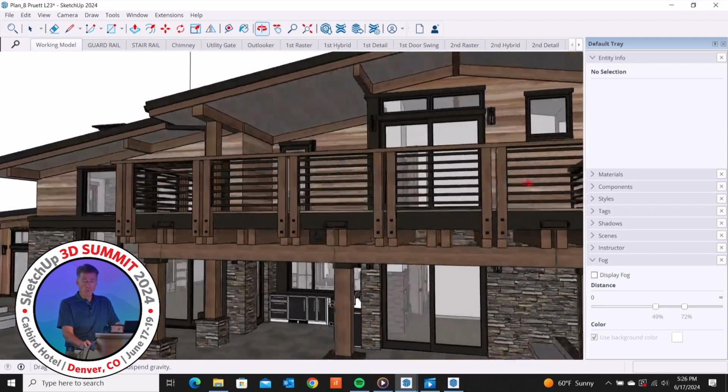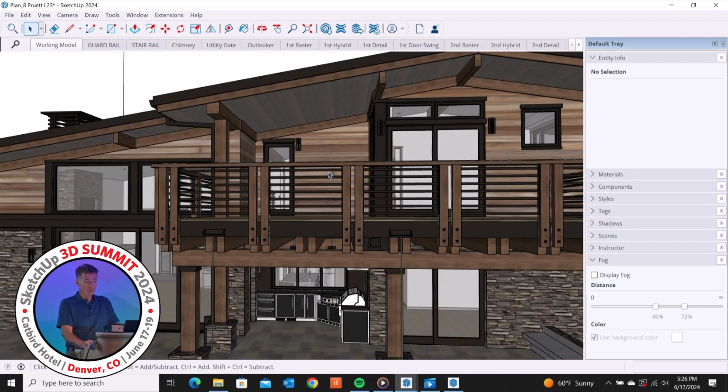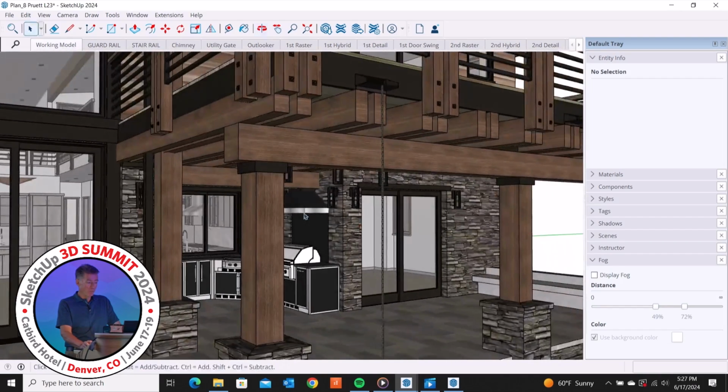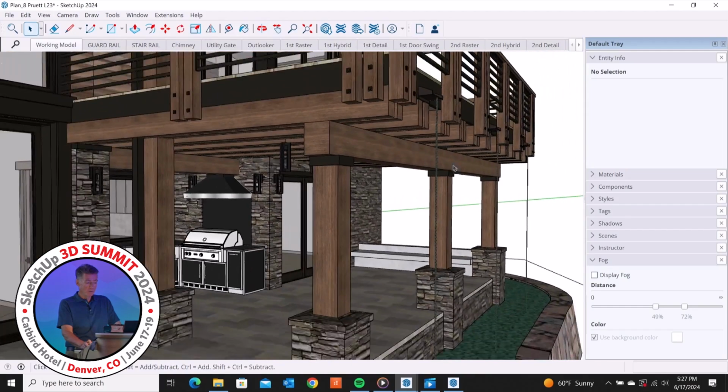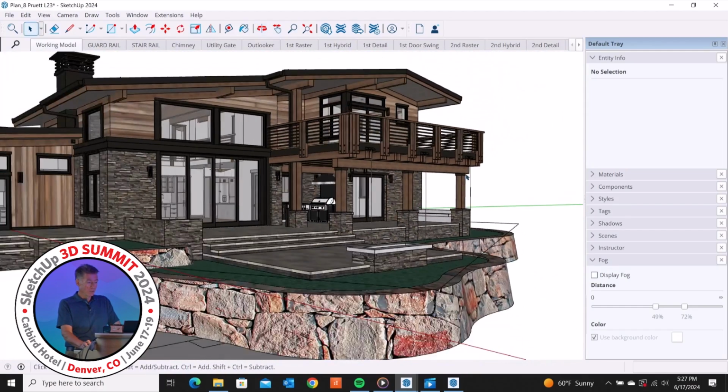You can see we use a lot of beefy wood where we are. We don't do any built-up headers, so all the headers on the interior are usually 6x12s. Even on small windows, it surprises me, they just throw 6x12s in there. These are all 6x6 posts. All these exterior posts are 12x12. That's a true timber, that's a 12x14. So a lot of big lumber. We used to be able to get Structural Select #1 for a reasonable price, and now we can't even get the material. So now we're just going DF1s.